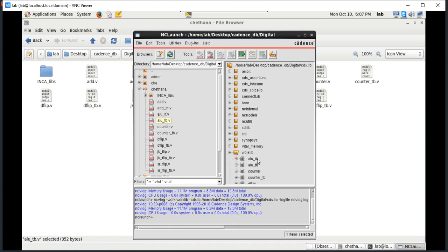Here this is the code, ALU, and the ALU test bench. This is the module name here. Now you click on the module name. Then the next tool will be highlighted, which is elaboration. Click on that. Again, if there are any errors, they will be displayed here. Next, consider the test bench. Elaborate the test bench program also. No errors. Now you can proceed to snapshots.